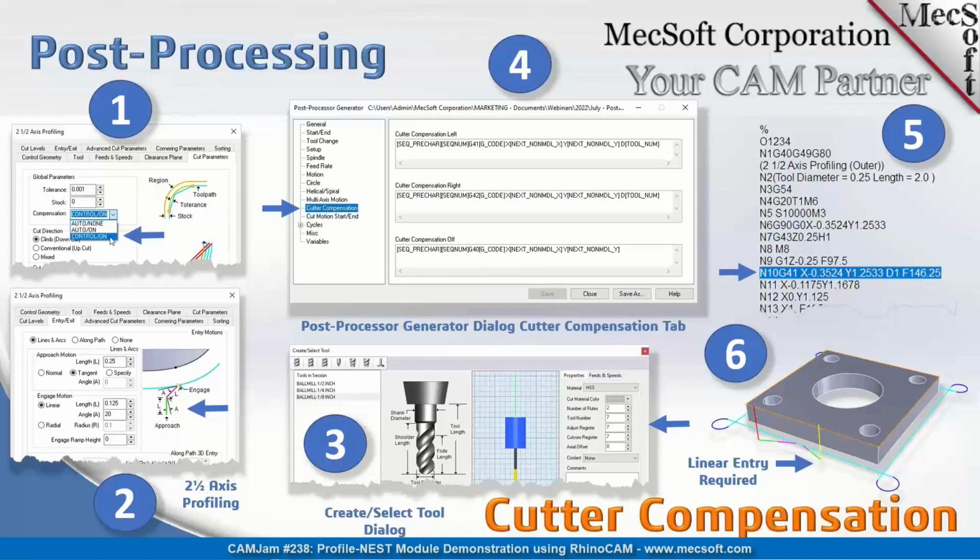totally accurate. You can make some adjustments at the controller for each tool to move that tool, give it some extra cutting offset, or typically it's in the positive direction, because if you have tool wear, you want to increase the diameter of your tool as it's defined in your controller.